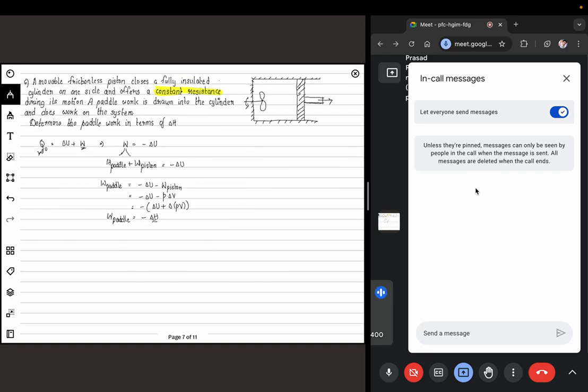In this problem, we encountered a case where the net heat transfer across the boundary is 0 since it is insulated. Then the net interaction that is happening is only work, and that is equal to the change in enthalpy. This is something that you might find tricky, but you'll understand later that any of the interactions that are happening at the boundary will have a certain relation with the change in enthalpy.